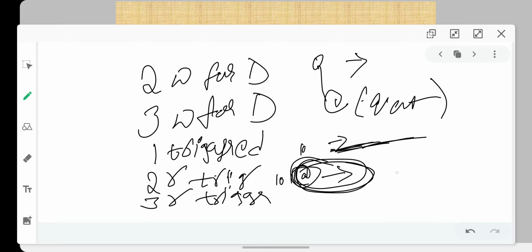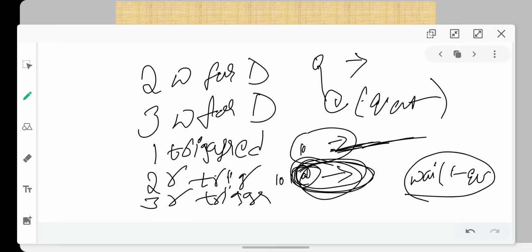In this place we are going to use the wait of event.triggered, where this wait statement is going to avoid the race conditions as well. Since both the trigger and the @ wait statement happen in the same simulation time, same time stamp, this wait statement can miss the trigger.